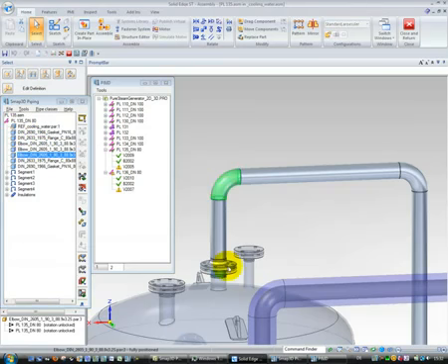With this information the software automatically places the required components from the pipe spec and the library in the background onto the pipeline path. Every component of the same fitting is the same part with a different occurrence. That means the part is placed just one time but at different positions. These things are all done when the software works through the progress bars step by step.